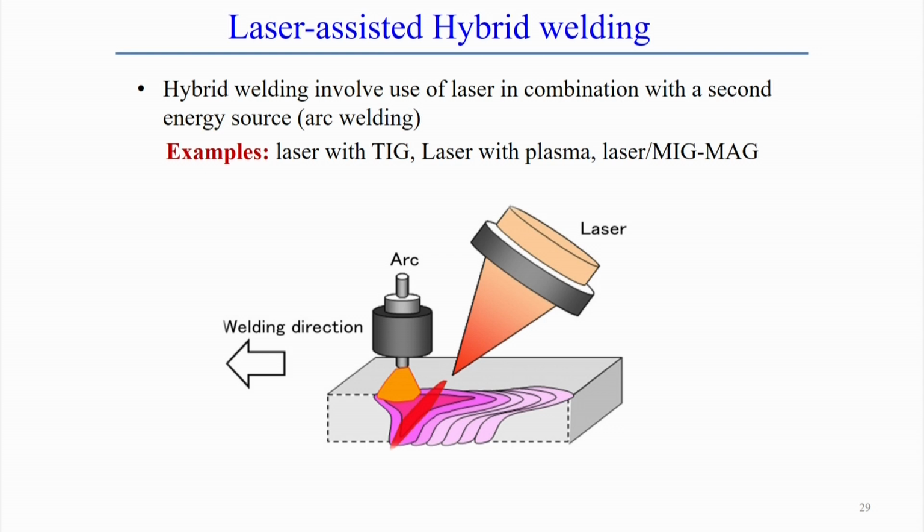The first main advantage is that we can create a large weld pool volume in general. Application of the laser focuses energy on a very small zone, and normally creates a keyhole formation, that means keyhole mode welding.